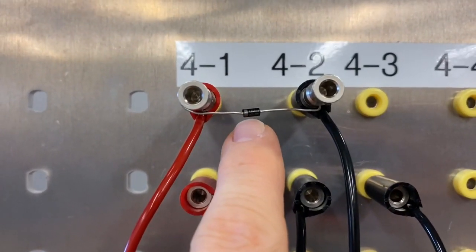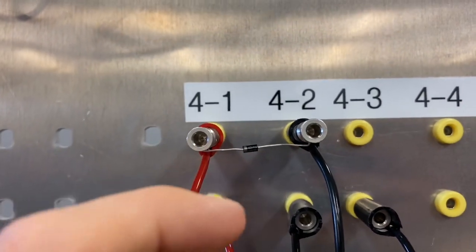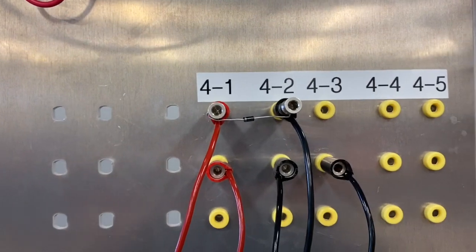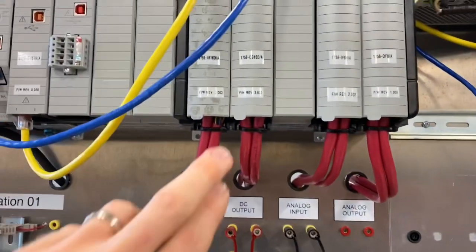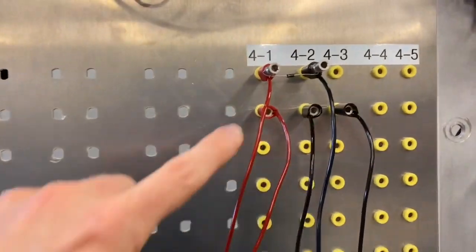You can see that gray band is going to the positive. That means no current will flow here during normal operation. But when the output shuts off, it'll allow current to flow backwards and dissipate. It'll just be a slight little pulse of current, and it will prevent us from over-ranging the voltage on our PLC and wrecking the discrete output. So that's what that is there for. It's for protection.